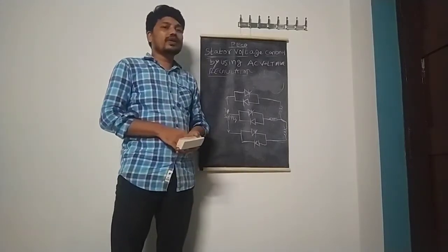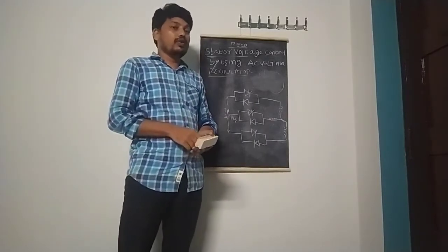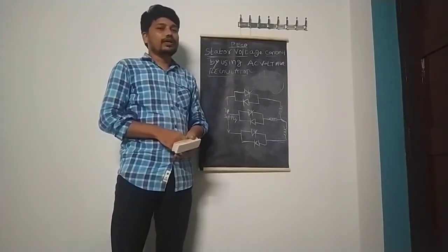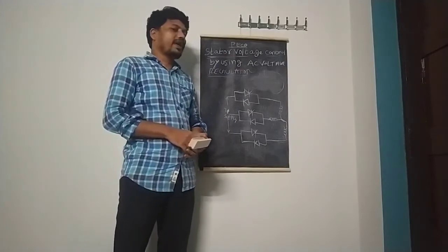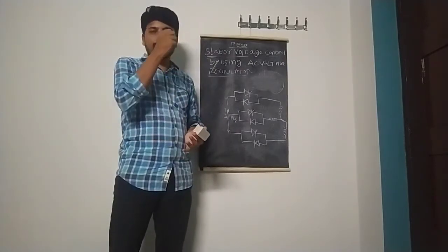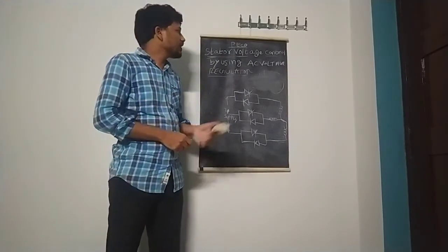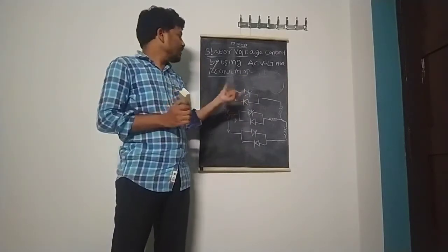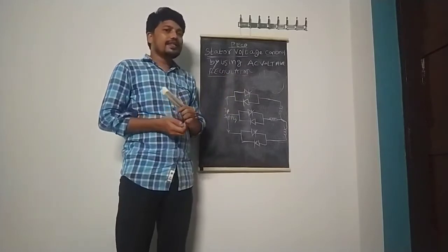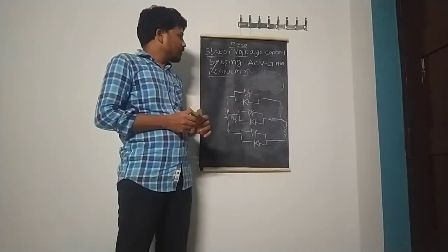In the case of the auto transformer, the cost involved is more, in some cases even compared to the motor. Therefore, both conventional methods, the three-phase auto transformer method and the primary resistors connected to the three-phase induction motor, are unsatisfactory in nature. So that's why we go for the next method, called stator voltage control with the help of the AC voltage regulator.